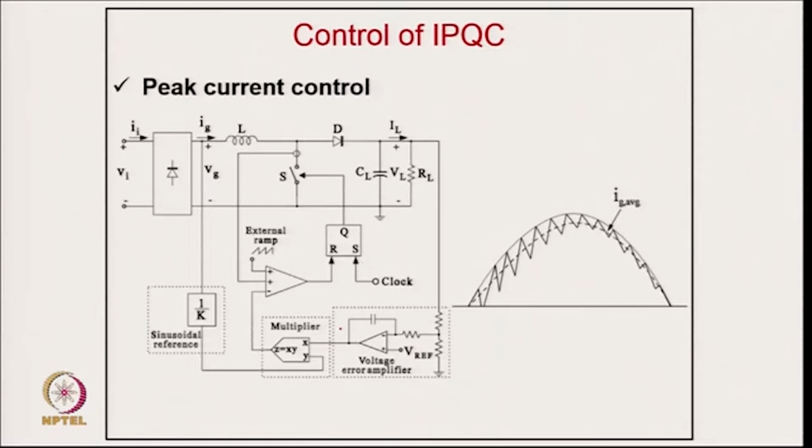So, the output of this we consider the amplitude of supply current, and we take the phase from sensing here, because these are the rectified voltage which have this shape. We take the shape from here, multiplied with the output of the controller, which you can call a current-like amplitude, and this is the phase.